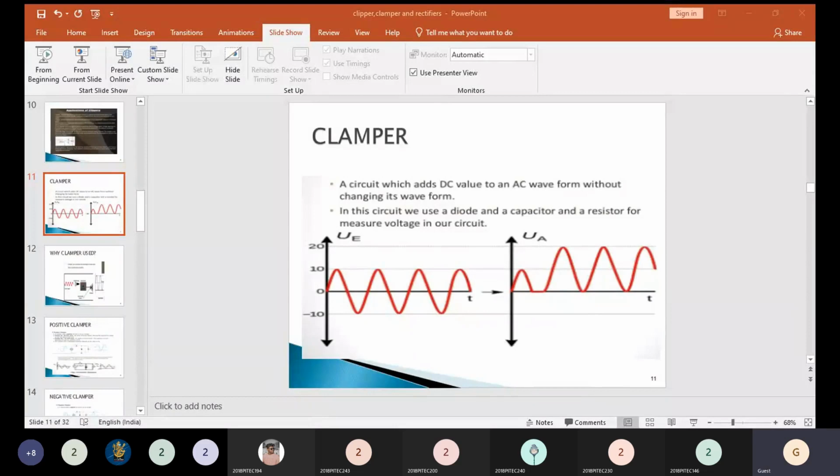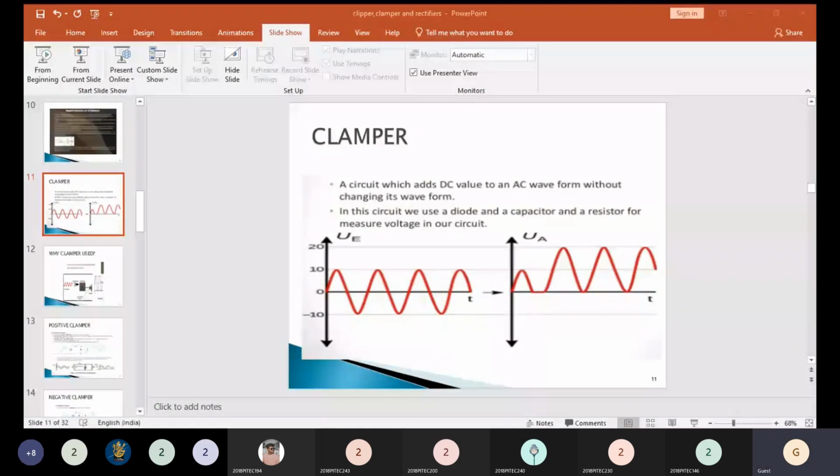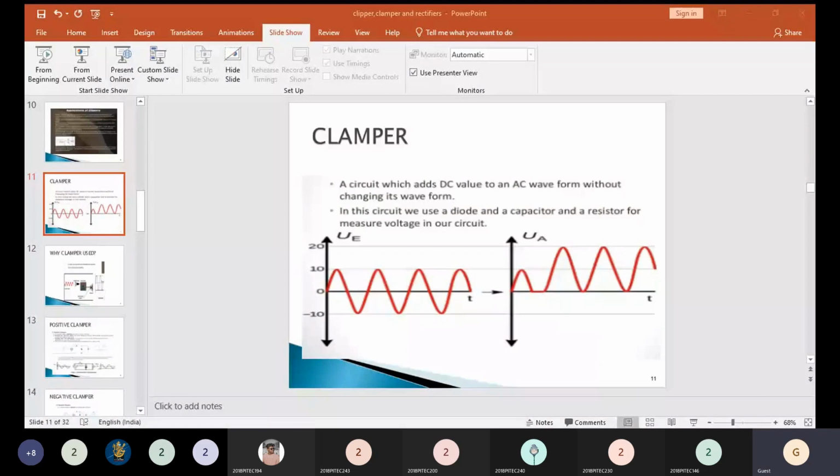Okay. This is a half-wave rectifier. In a half-wave rectifier there is only one diode. The input signal is Vm sin omega t. Only one diode is used, along with the load resistance RL. Now we replace the diode with its forward resistance RF. So what is the equation for the average or DC current of this half-wave rectifier?